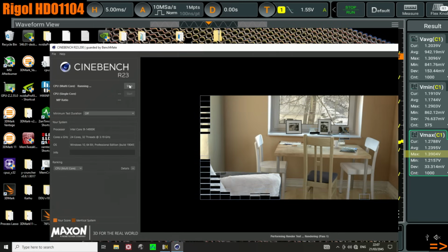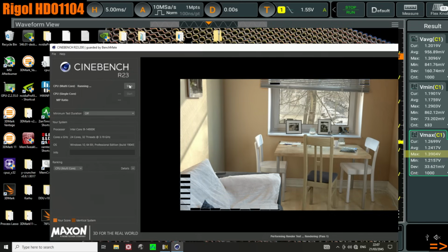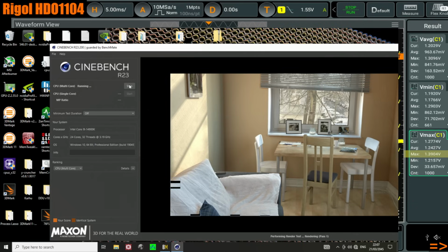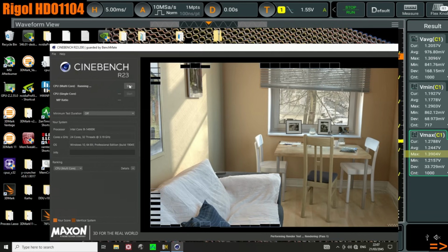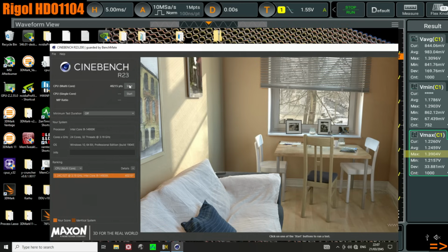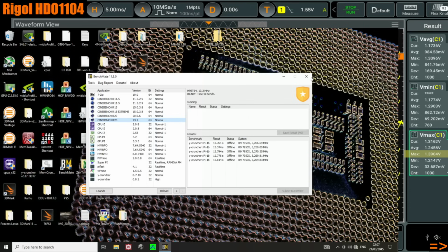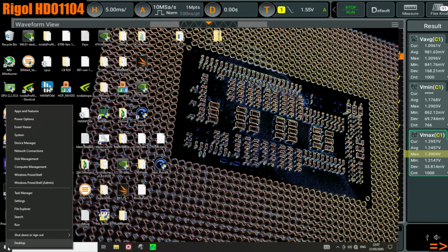So if you don't want to spend a whole bunch of time verifying that your CPU isn't going to randomly crash or cause weird issues, just undervolt it less. That's the main reason I really wish this motherboard had a voltage limit, because then you wouldn't need to undervolt to get the voltages under control. You could just set a voltage limit. But apparently that's too much for MSI.